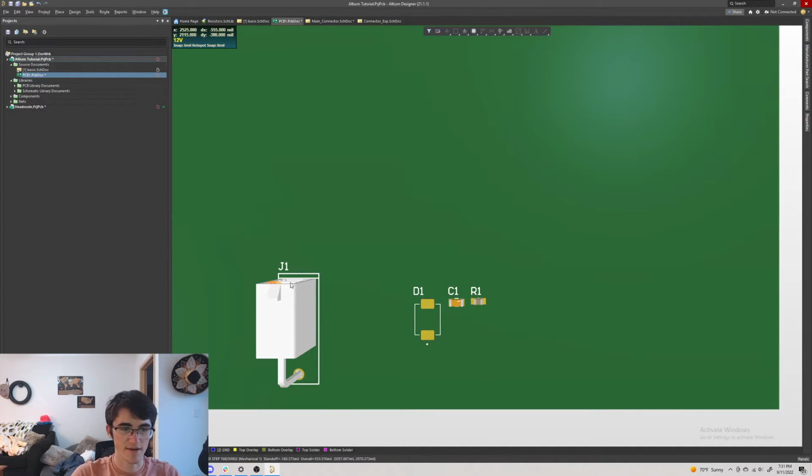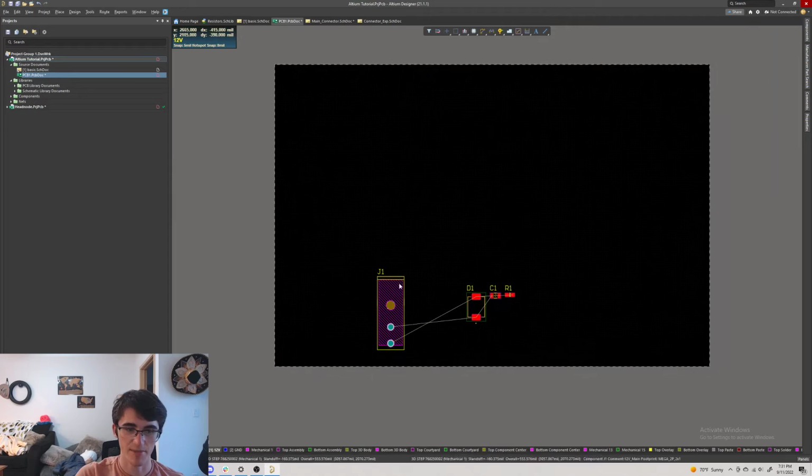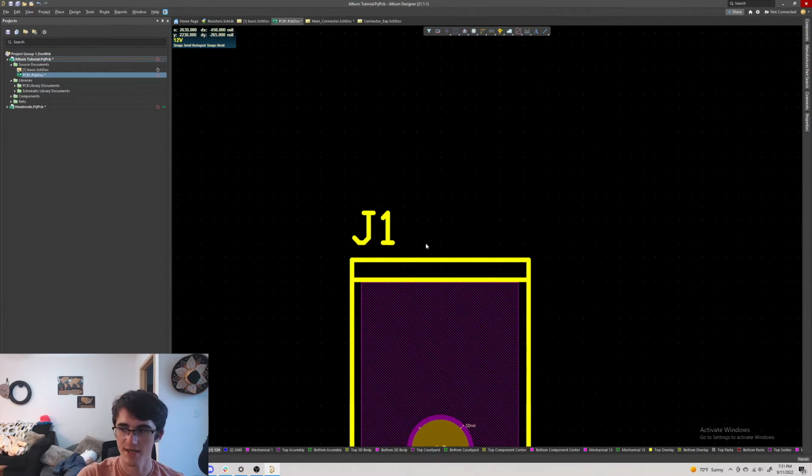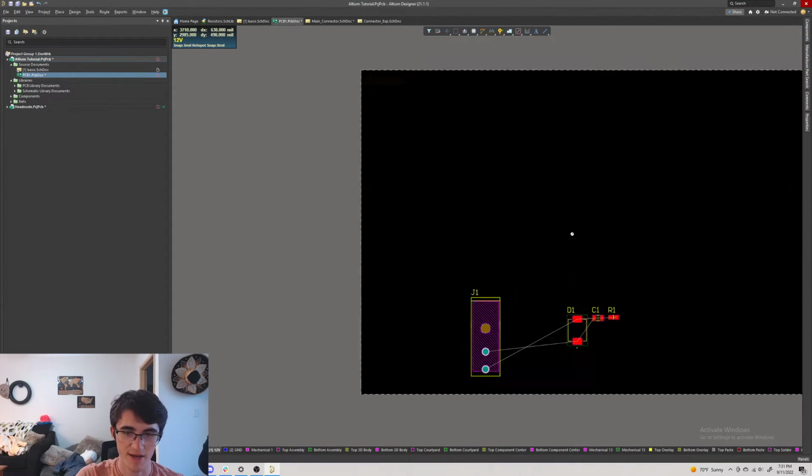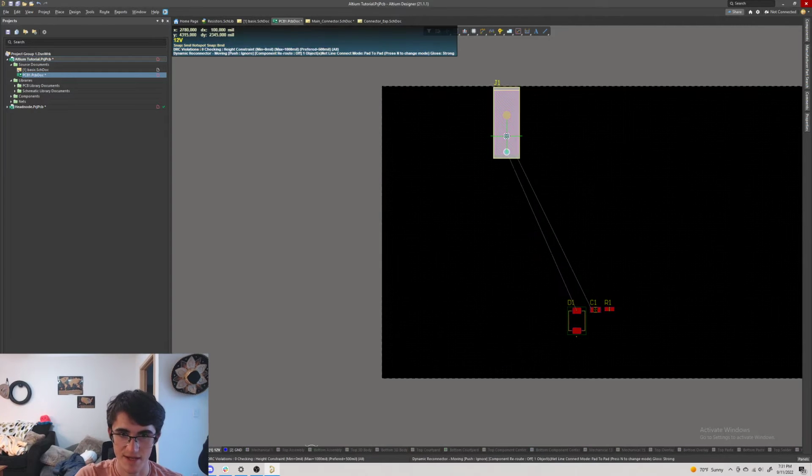But yeah, like I said, generally you want to put your connectors on the outside of the board. You can see here that the external part of the connector that's going out of the board is on the top here, and you can see that with this little mark right here. That's just something we have with our Megafit connectors, or all those types of connectors.